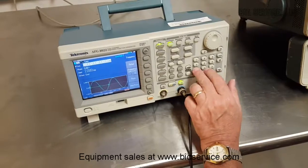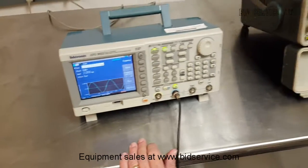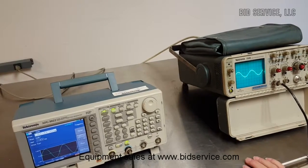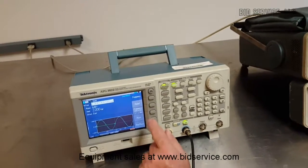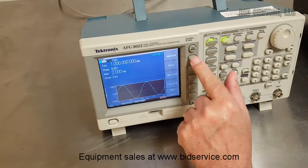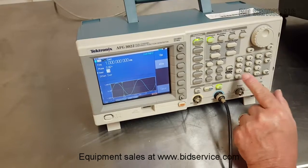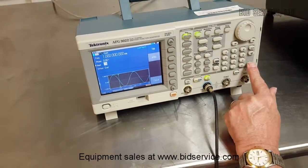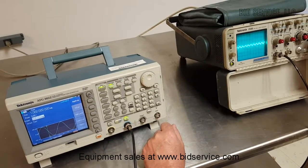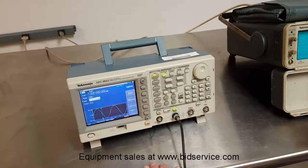I'm going to go to 1 kilohertz on this one. And you can see I have to make a large adjustment here since I'm going at a much slower speed. And then I'm going to change my amplitude. So I'm going to go back to the top menu. Amplitude, amplitude, and again I'm going to go to 0.5 volts peak to peak, and you'll be able to see the change over here. So again, the waveform has decreased proportionally, and I can increase that, of course, to 6.